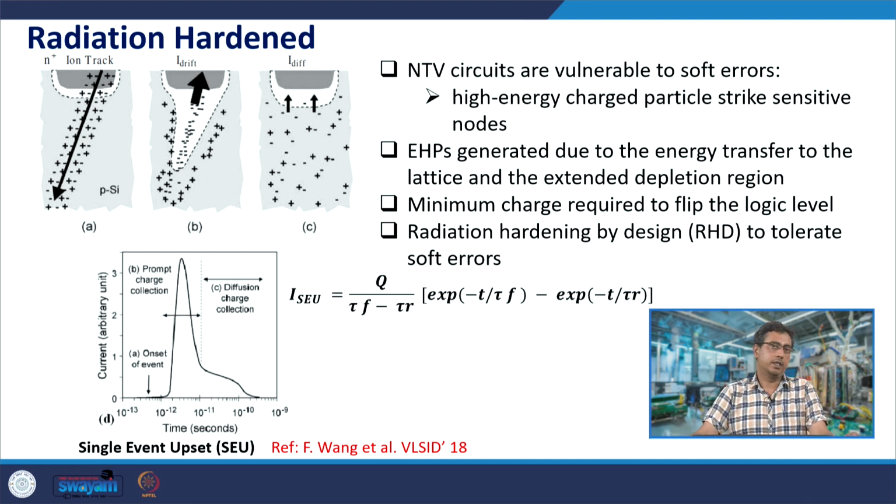The load capacitances store smaller charge values. Because VDD is small, CVDD is also small in near threshold circuits. So, smaller charges are present. If the value of the charge changes because of, say, charged particles from ambient radiation, the change in charge on the capacitances at different nodes is much larger because the charge itself was smaller. And small changes in voltage would cause exponential changes in currents. Therefore, for these reasons, radiation effects in near threshold voltage circuits are much more significant when compared with those in conventional nominal voltage circuits.